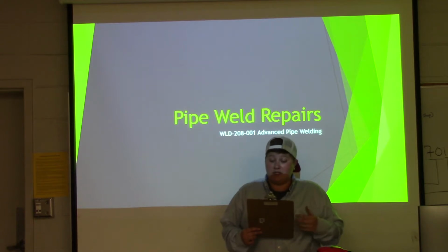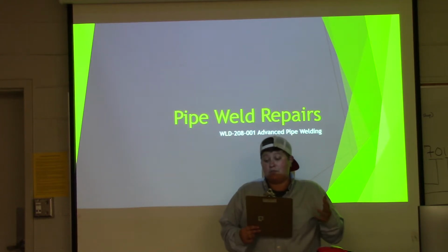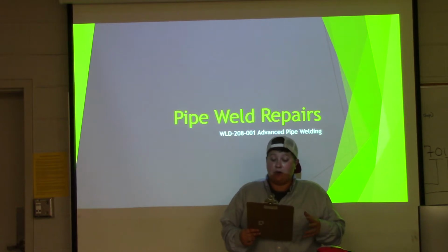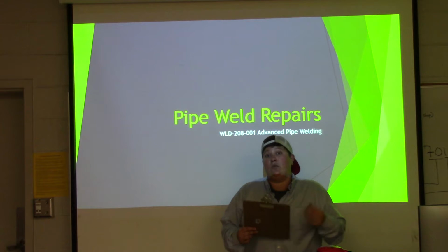Was it your tungsten was sticking out too far? Was there some rust or mill scale that you didn't grind off all the way? You have to start thinking one step ahead. Eventually, you won't have to do as many weld repairs after practice and experience, but while you're still learning and still in school, you have to start understanding why.